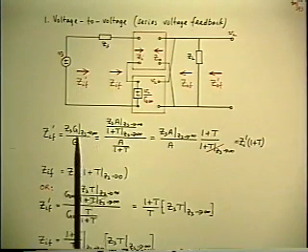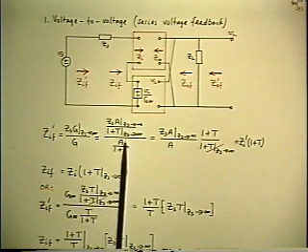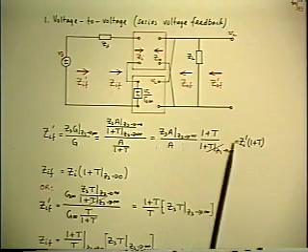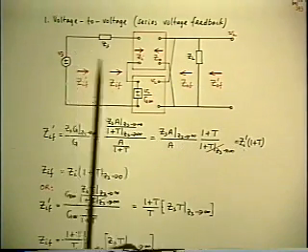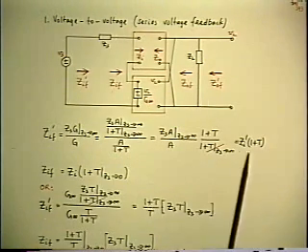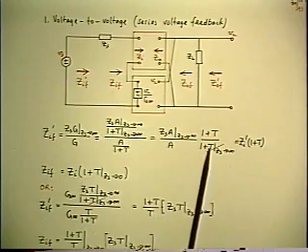So all you do is substitute for G equals A over 1 plus T, take the limits factor by factor, group the A terms together, and identify them as the outside input impedance before feedback, Zi prime. Look at what's left.